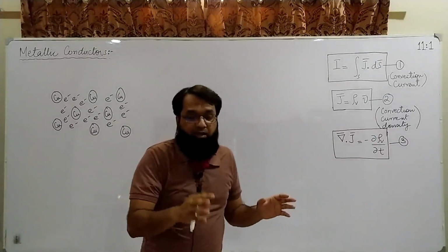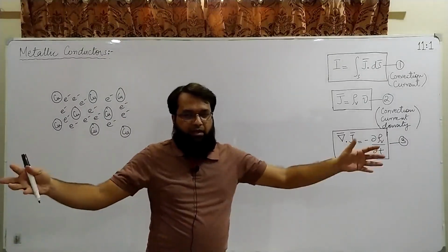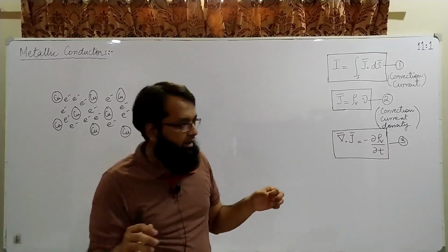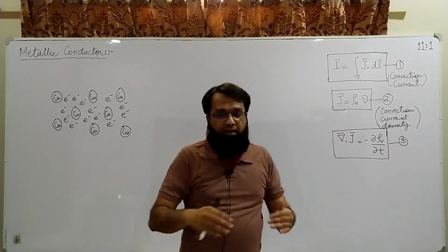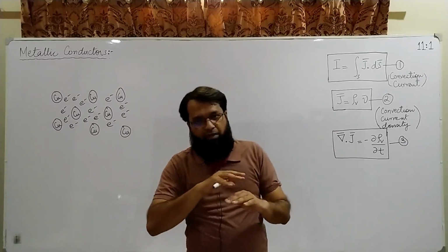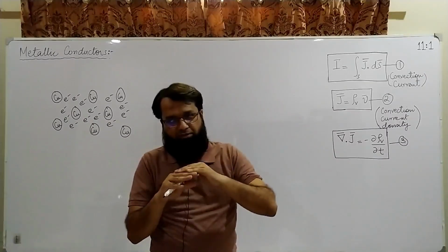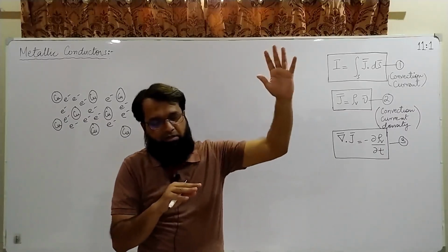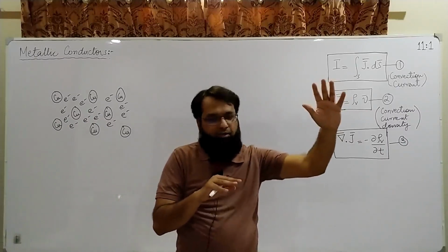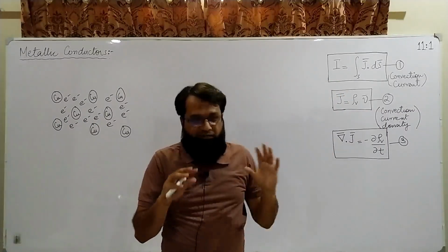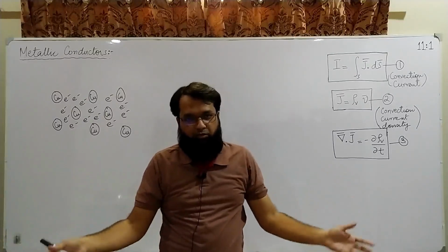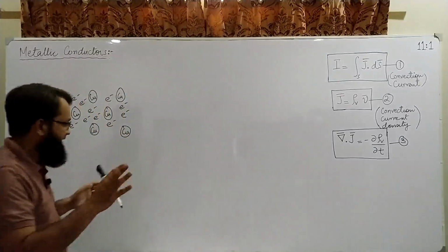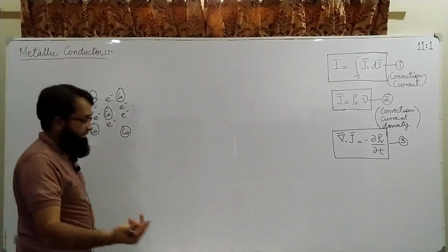It is quite possible that insulators acquire energy from the surroundings, from some electric field, and that energy is so much that the valence electrons in the insulators cross the potential barrier or the forbidden region, and they jump to the conduction band. If it happens, we say that insulator breakdown has occurred. So in that case, the insulator will behave as a conductor.